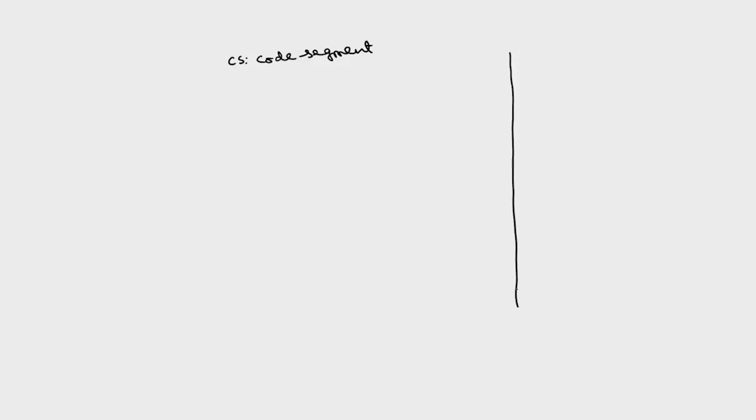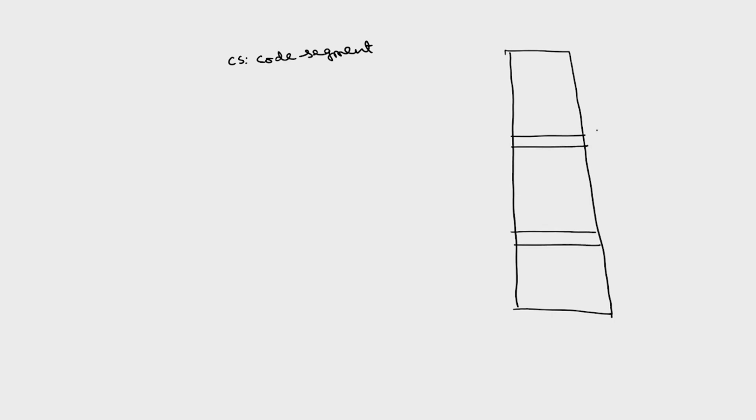So, if I take a code segment with 64 kilobytes of memory out of this 1 megabyte, suppose I use from here to here, this is one location, this is another location, this total capacity is 64 kilobytes. So, the starting address is here, some 50000H. In case of 64 kilobytes, the ending address will be 5FFFFH. So, how to find this out? This is the code segment.